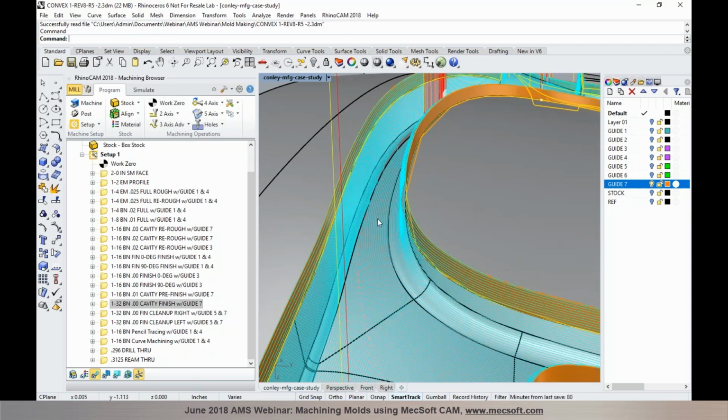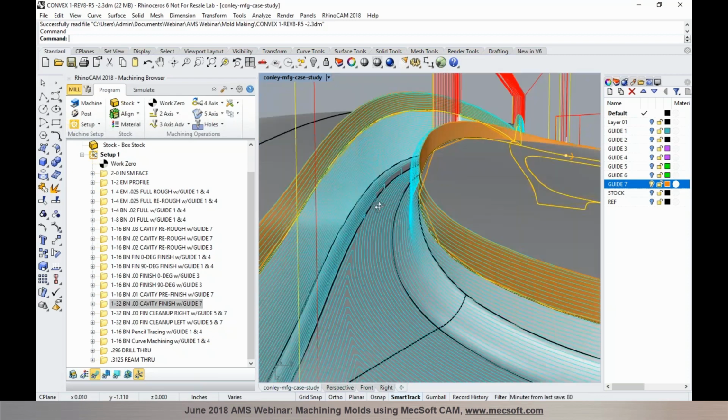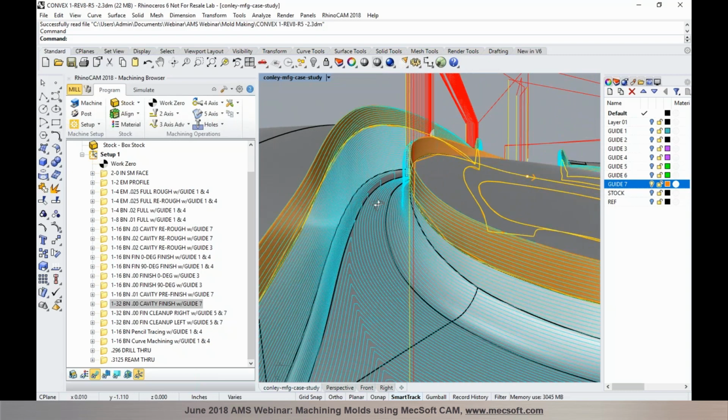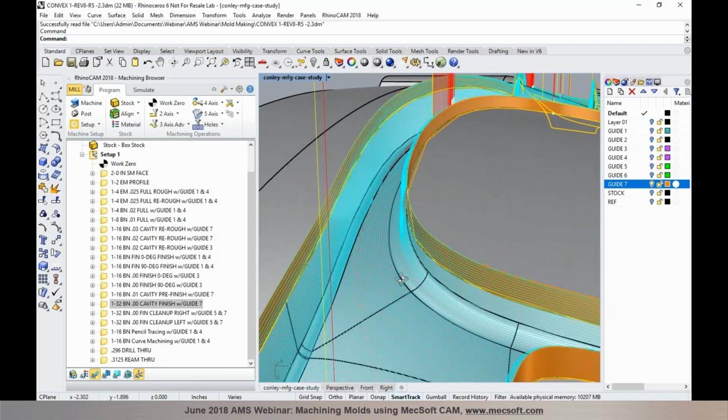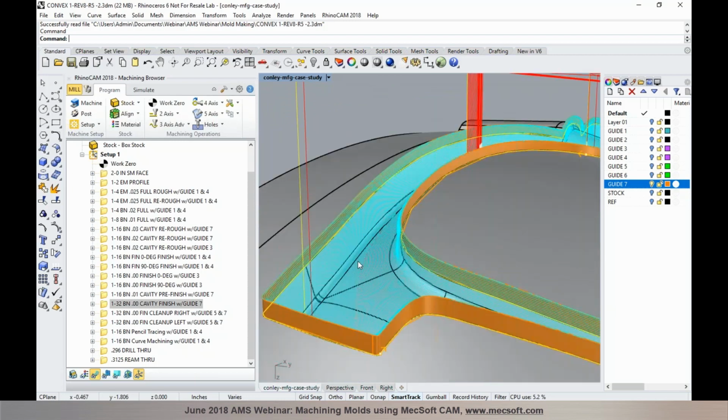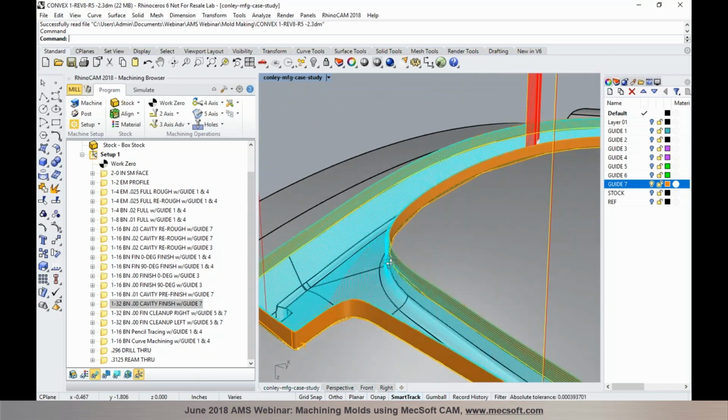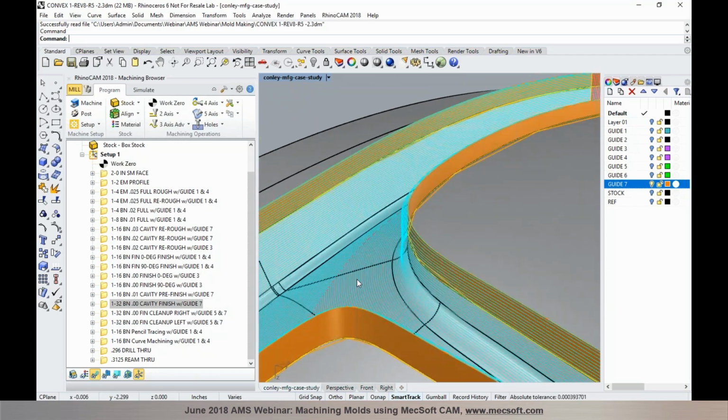toolpath. And this particular method, which is offered in our Pro and Premium configurations, you will notice that the generated toolpath creates a uniform 3D step over. This technique is also known as constant scallop machining, or also known as 3D offset pocketing. This would result in a very nice finish and produce great toolpaths when you're working with mold cavities or mold core features in here.